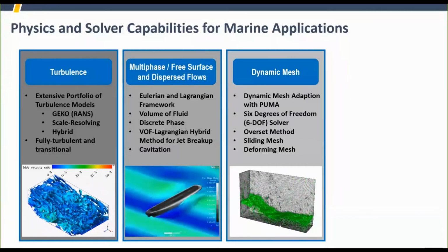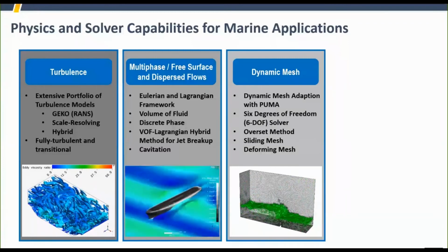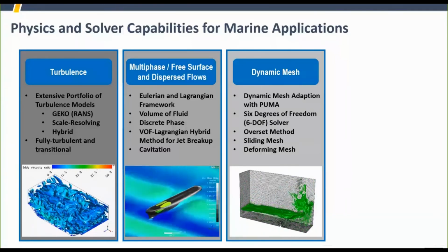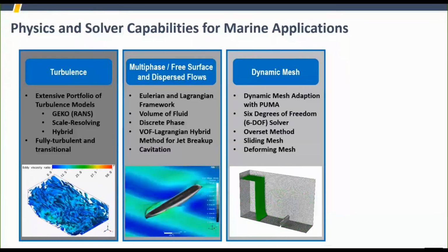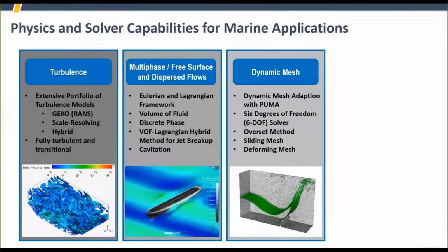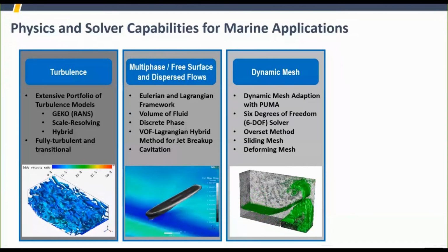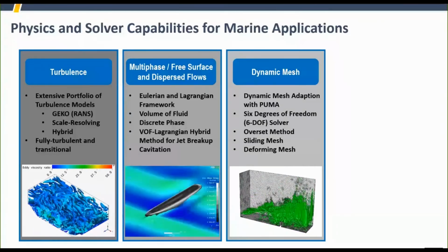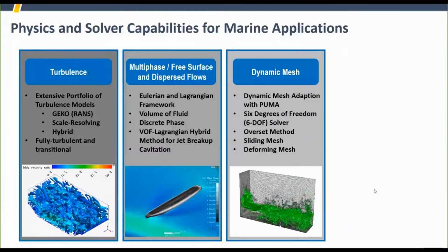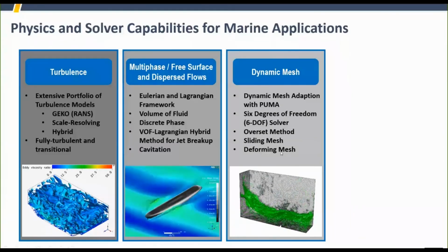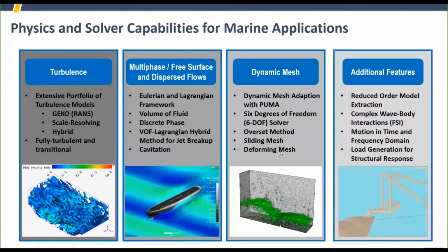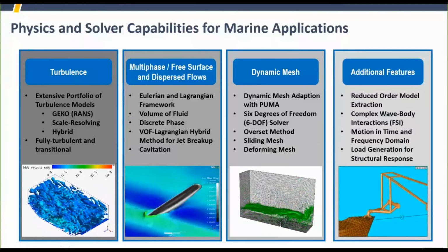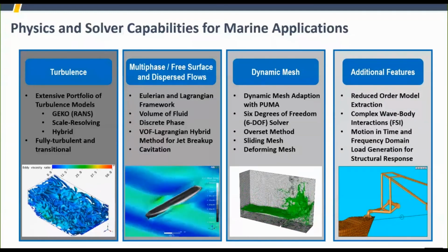The additional features that are needed for this type of simulation include the ability to take this very detailed model that could take hours or perhaps a few days and extract the essence of it into a reduced order model, which can then run multiple orders of magnitude faster than the CFD model, and yet retain and utilize the major or the main findings from the CFD model.